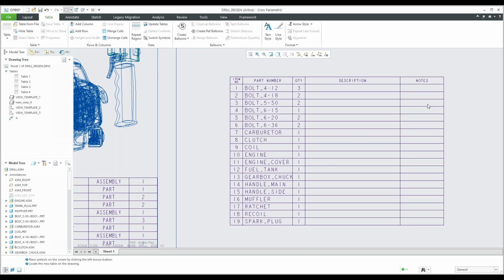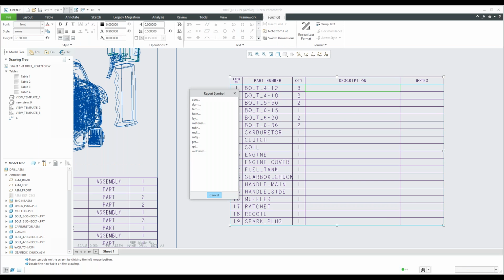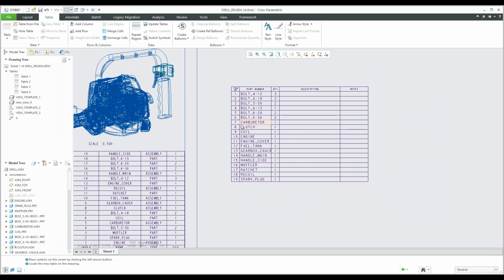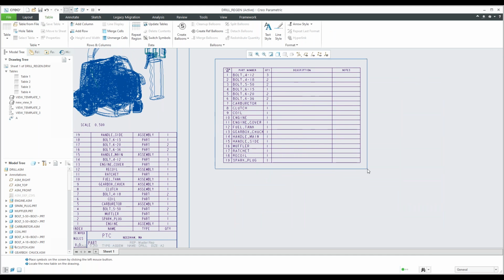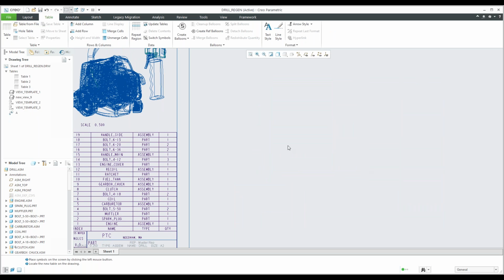It created the bill of material, but obviously there weren't descriptions and things like that in here. So I can go and I can add information, a certain parameter, into that repeat region. Okay. So now you're going to ask me, so how do we do that? Or how do we create that repeat region? So let's delete this quickly and let's build one.